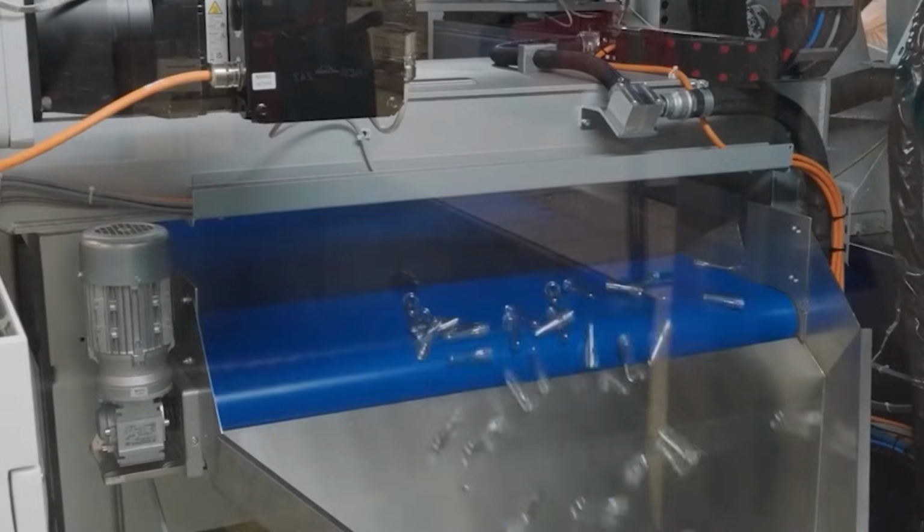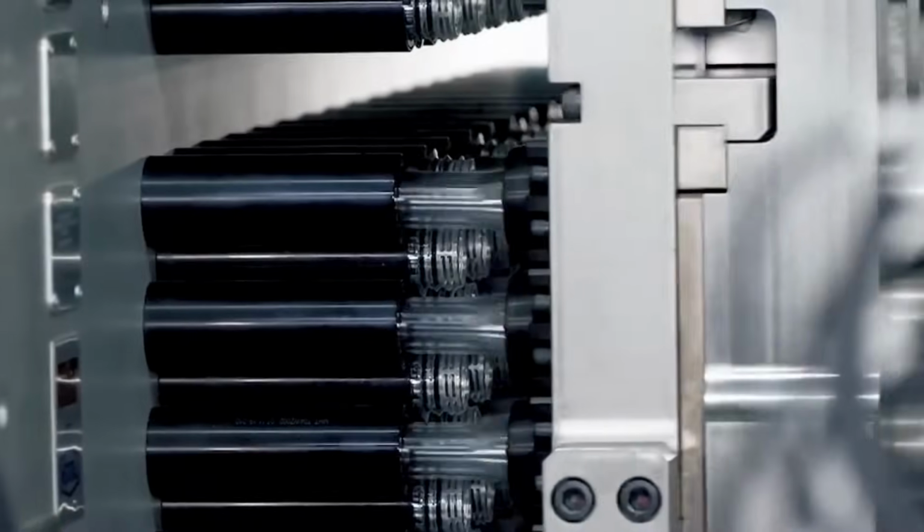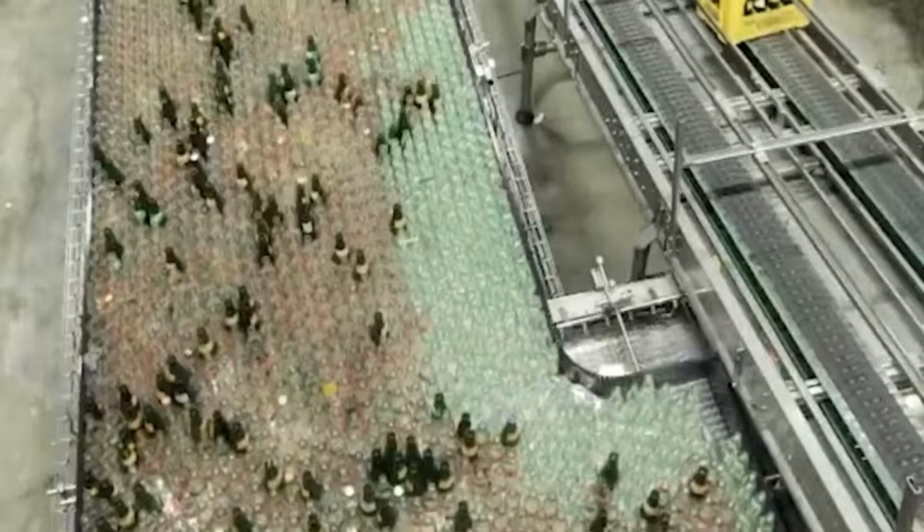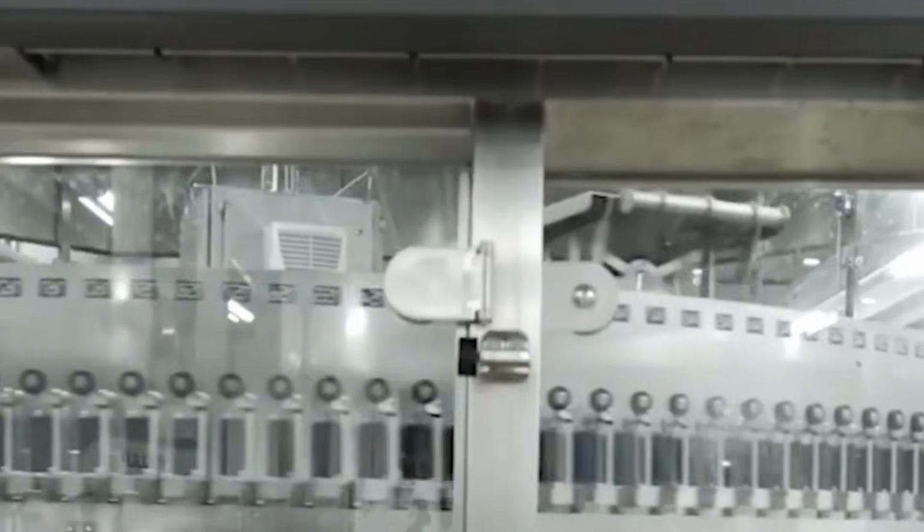Carbonation takes place in a pressurized tank equipped with high-efficiency diffusers. Liquid CO2 is injected under controlled pressure through stainless steel sparges that break the gas into fine microbubbles. As these bubbles rise through the cold beverage, the carbon dioxide dissolves into the liquid under saturation pressure.